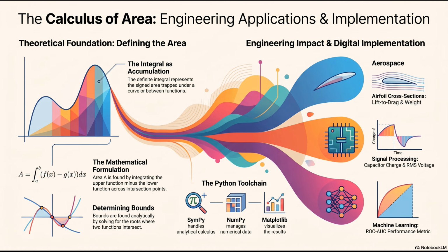Right. And when you do that, the area units cancel each other out, and you are left with force multiplied by distance. Wait, and force times distance is the literal physics definition of work. Precisely. The geometric area trapped inside that thermodynamic loop on a piece of paper is a direct one-to-one calculation of the mechanical energy that the jet engine will produce in the real world.